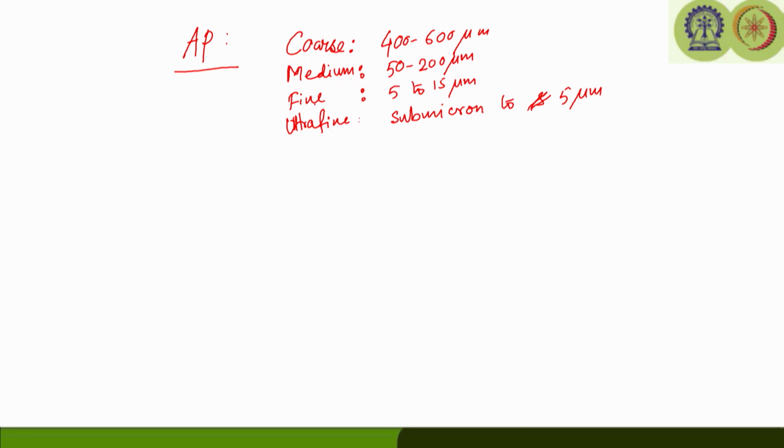Generally, we want to improve the loading fraction or the packing fraction. Packing fraction means minimizing the volume of the solid particles. Somehow we have to improve the packing of the solid particles within the rocket motor. So, this fraction is the volume of the solids when packed to its minimum volume. That is a theoretical condition.